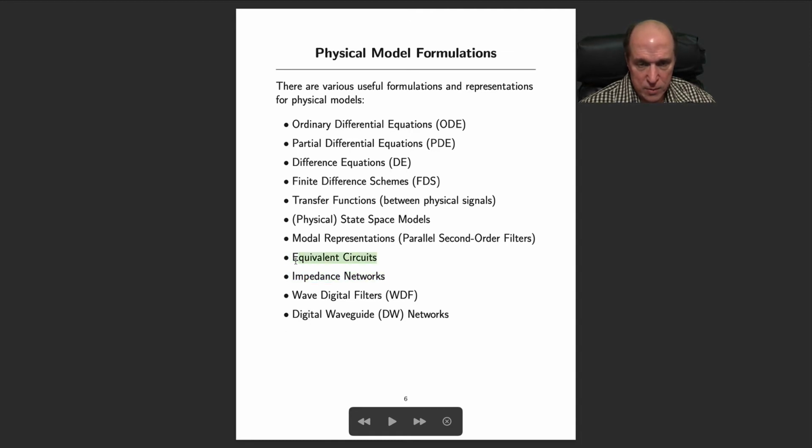Once you have your equivalent circuit, you can now replace every element in the circuit by its impedance. And if it's a linear time invariant circuit, you can do very elementary resistor analysis of the network, because you can manipulate the complex impedances of things like inductors and capacitors as if they were resistors when you're in this impedance space. It's like taking the Laplace transform of everything, and in the differential equation space, it turns the differential equation into an algebraic equation. So your ordinary differential equation just becomes a polynomial in s for the analog, continuous-time case, and a polynomial in z for discrete time, and those are a lot easier to work with.